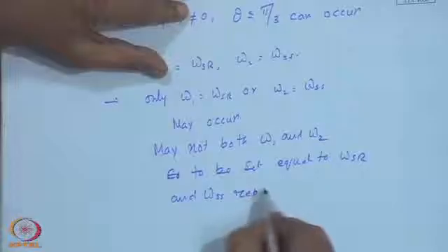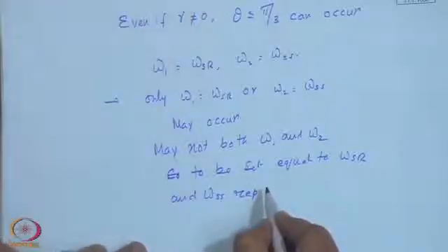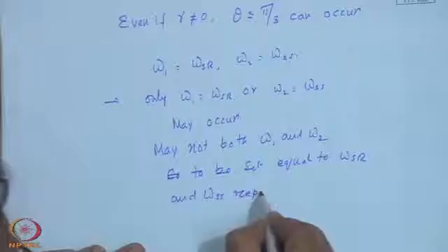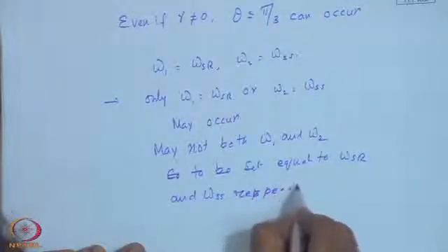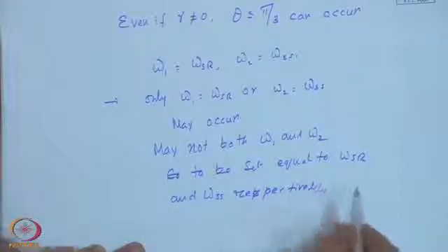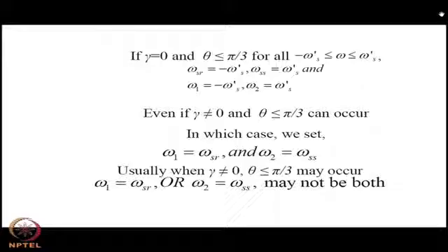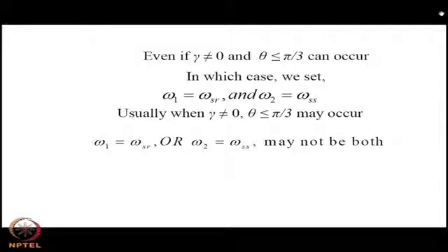In other words, if it is due west, it is possible that theta greater than 60 may occur in the forenoon and may not occur in the afternoon. So, let me repeat, this piecewise integration has become necessary because of the description for tau alpha by tau alpha normal being set in two intervals for the angle of incidence theta.